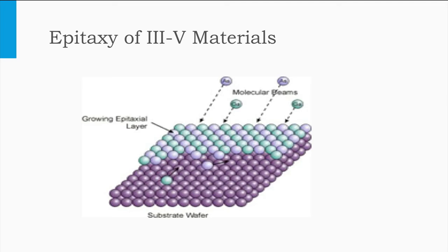The substrate is usually a germanium substrate. The gallium arsenide crystalline lattice is grown layer by layer and adopts the structure of the crystalline substrate. The relatively slow layer by layer growth allows the deposition of compact materials without any vacancy defects. Furthermore, processing at high vacuum conditions prevents the incorporation of impurities. Dopants can be added to make it N-type or P-type. 3-5 semiconductors can be deposited up to a very high degree of purity.